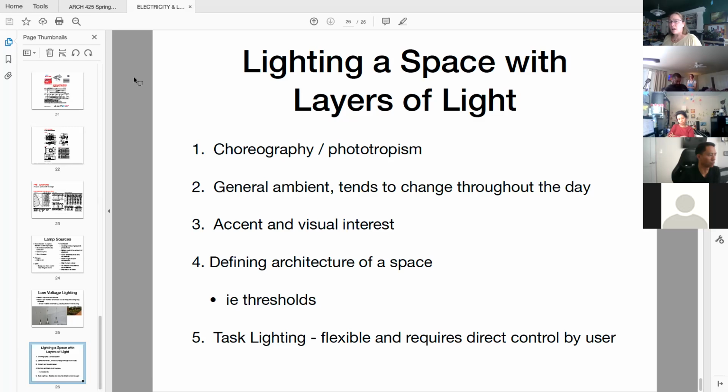So that's something not an awful lot of architects think about, but think about how you enter a building and what the lighting level is on the outside and what it's like when you come in the door. Or if you're moving from a great room to a study in a residence, is that going to be more of a quiet feel, where the fireplace is, versus the family room where there's a lot of activity and you've got a lot of motion going on? Use your light levels or your lighting fixtures and how you place them to enhance the difference of the space.